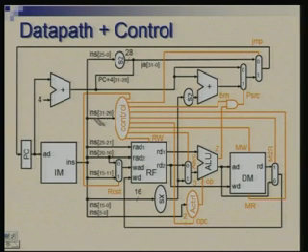So, this circuit is predominantly looking at the opcode field, whereas this is predominantly looking at the function field, and some additional information it requires about opcode is being actually processed by this and made available here, right. So, after having done this, what remains is basically to look at design of this and design of this. If you can enumerate what outputs you require for what inputs, you can do it in a straightforward manner, and same thing here. So, we will take it up in the next class.